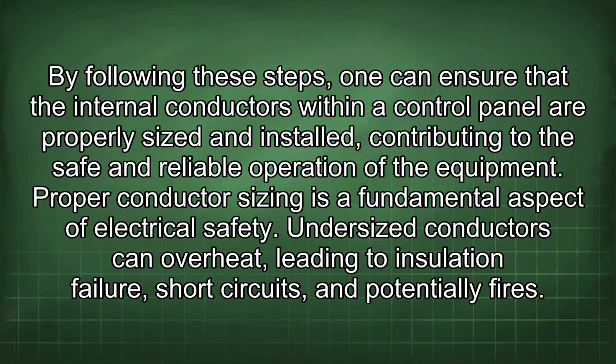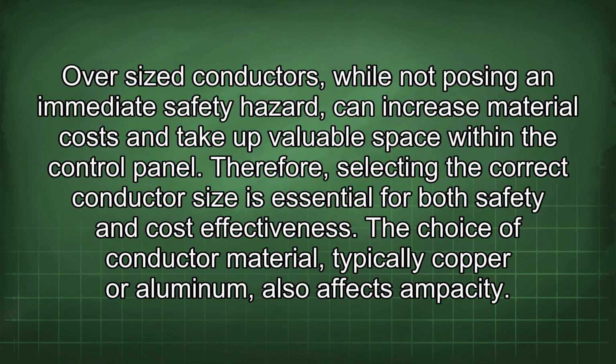Undersized conductors can overheat, leading to insulation failure, short circuits, and potentially fires. Oversized conductors, while not posing an immediate safety hazard, can increase material costs and take up valuable space within the control panel. Therefore, selecting the correct conductor size is essential for both safety and cost effectiveness.